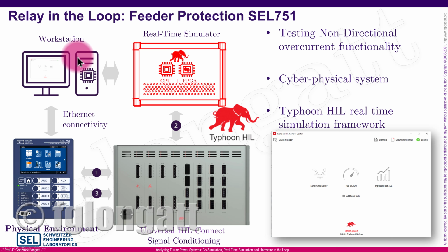The setup is very simple. We have here at the top the workstation that we are controlling, and we have all the software. Then we have the real-time simulator where the differential algebraic model is solved, and we are sending signals to the huge elephant over here, the Universal HIL Connect, and finally closing the loop with the Schweitzer Engineering Laboratories SEL 751, the overcurrent protection, okay?